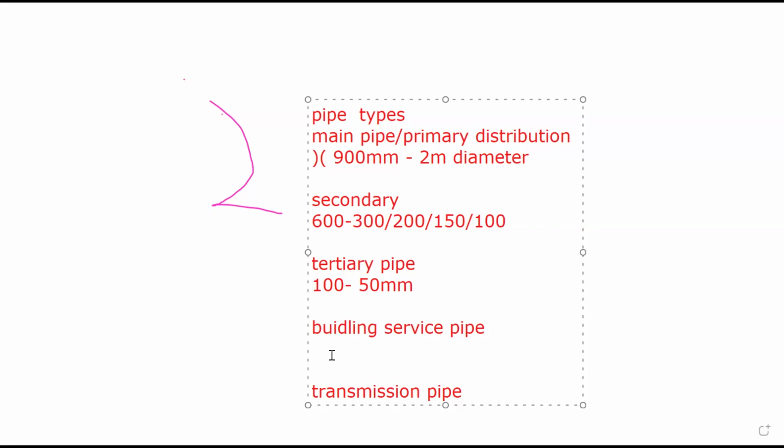Pump test means you pump the water, you bring a tank, you bring a generator, you bring a hose or a pipe, you reduce the discharge of the water to a certain volume and allow it to run over some hours. Then, if it can last for 24 hours, it's a good yield.